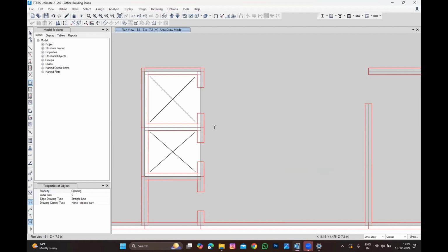We are not talking about in-plane movement, because there we do have connections to the slabs. His concern is correct, because the waist slabs we are not going to connect. Only the landing is going to connect. But even if it is not connected, if it touches, definitely it will not bend; it will bend only between the base levels of the wall.